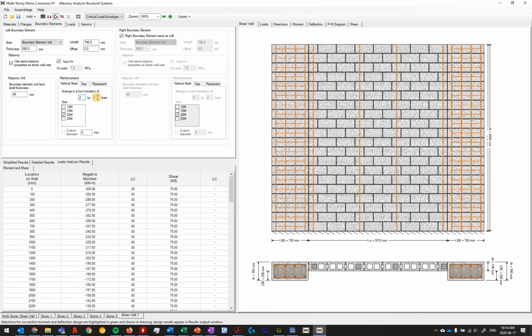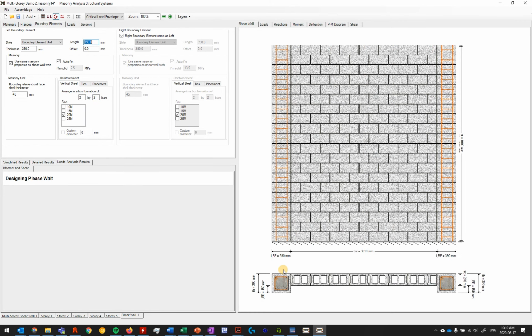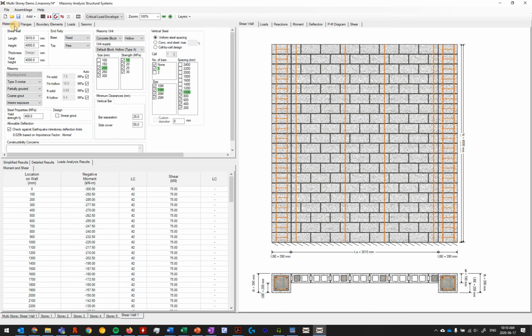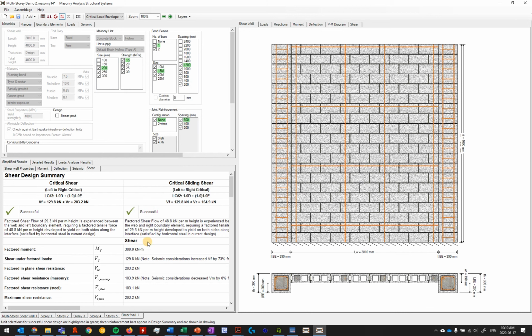There's a lot that you can do here, but basically, when you start getting into ductility verifications, sometimes the issue is looking at the layout of your structure or different issues that you have. But in some cases, we can actually achieve higher compressive strains by having this confined area of grouted masonry here. And there's a lot of research that's gone into that, and it's now in the Canadian design standard, the S304. Since it's in a standard, we were able to put that in the software. Like I said, this isn't really a full tutorial on everything having to do with it. However, the software does go ahead and perform these designs for you, including when it goes through and checks it for shear and everything as well.